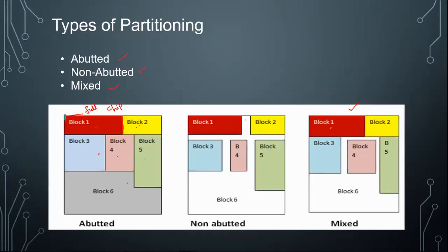For example, I have some glue logic. Glue logic is nothing but spare logic which does not belong to any block, any block in the given partitioned blocks only. So I have some module, and I don't want to place it in module 3 or module 4. I want to place it between these two. So I can give some channel here, place all of this here, and make the connectivity. That's how we have to decide.